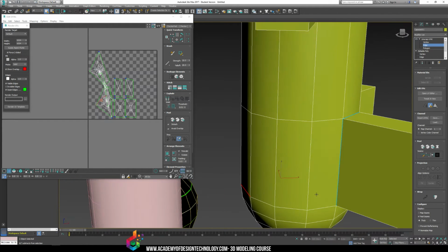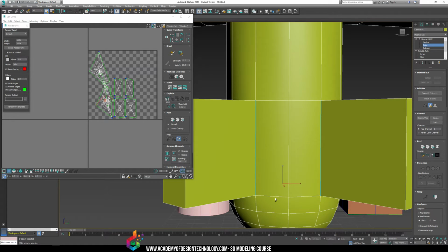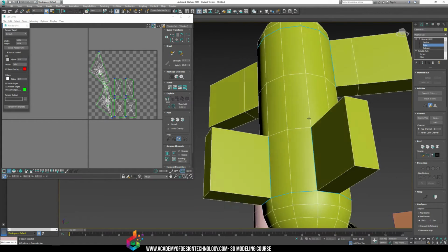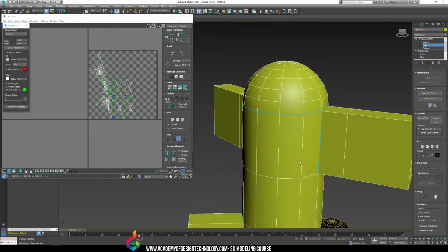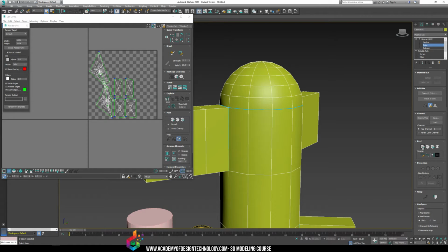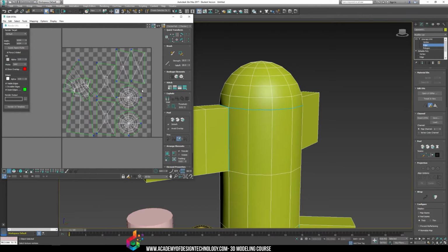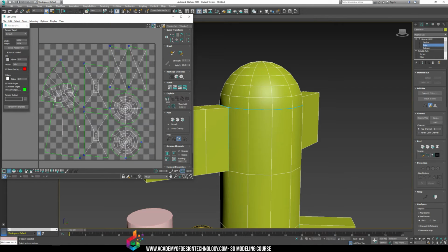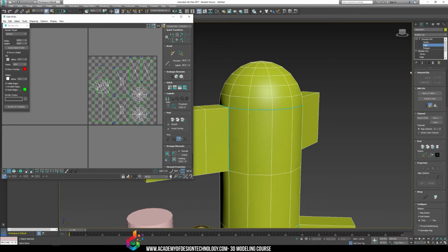So that means I should have 4 arms, the bottom of my capsule, and the top of my capsule. And don't forget to click convert edges to seams so that these lines are all blue. See, blue lines down there, blue lines up here, blue lines cut that. And now I'm going to go to quick peel, and we can see we're getting a much better shape. You can see the top part of the capsule, the bottom, the arms here. And now we just need a little bit of unwrapping work to get the capsule looking right.